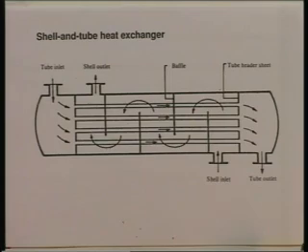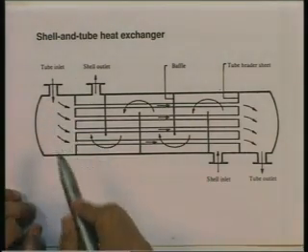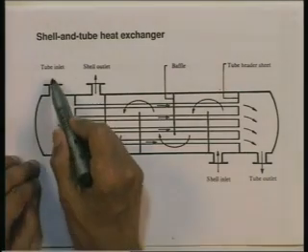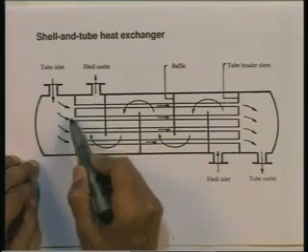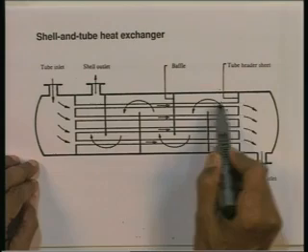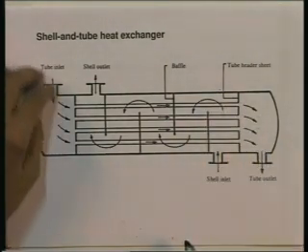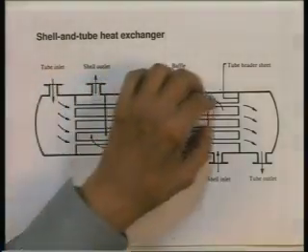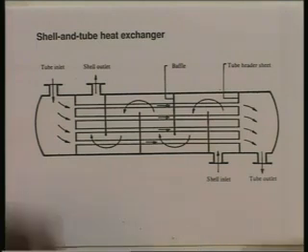All right. One fluid flows inside the tubes, and that is the fluid that I am showing here, entering here. The flow is breaking up into 4 parts, going through each of the tubes, coming out here and then going out. So, this is one fluid flowing inside the tubes. The other fluid flows on the shell side, that is outside the tubes.